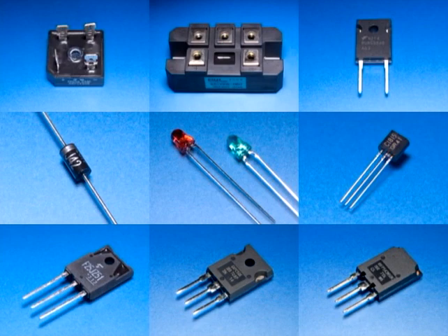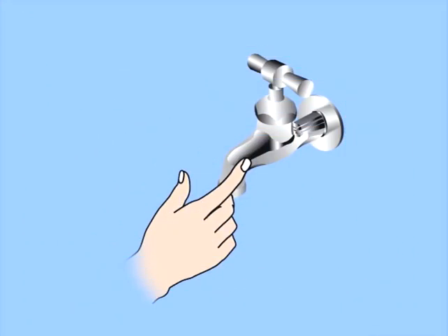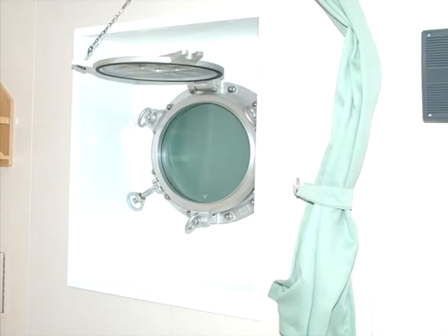To prevent electrostatic destruction, it is necessary to remove static electricity from the body prior to handling a semiconductor device or electronic circuit board. It is easy to rid yourself of static electricity. One simple method is to touch a tap with your bare hand. When on board ship, you can touch the steel deck, floor, or ship side for several seconds with your bare hand. However, touching an FRP wall surface or glass can actually build up static electricity.